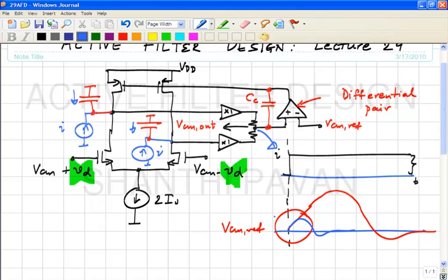As the integrating capacitors are made smaller and smaller, the slope will become higher and higher, and eventually the slope will tend to... Slope is I by C, C is tending to 0, so it goes to infinity, right? So if you put a step current into a node and you see that the voltage jumps up to infinity, what kind of impedance is there?